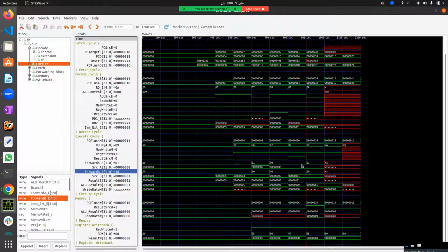So you can see that we got an update of the forward E signal. Let's get 0, 1 from the write back stage, because at the time we are writing a 0 value at the load 1 instruction. So we are writing a 0 value to its memory location, and again 1, 0. So we are getting the bypass from our memory stage. So we get the bypass results, and we have just added 0 plus 1, and we get our final result of 0 plus 1.